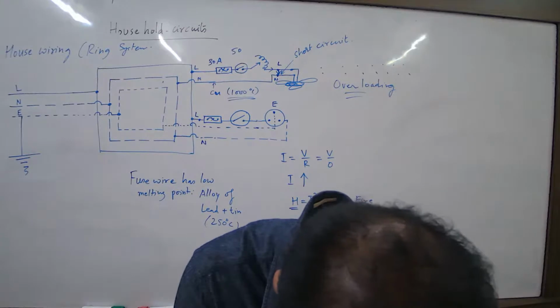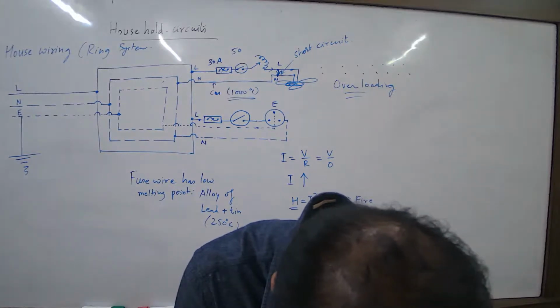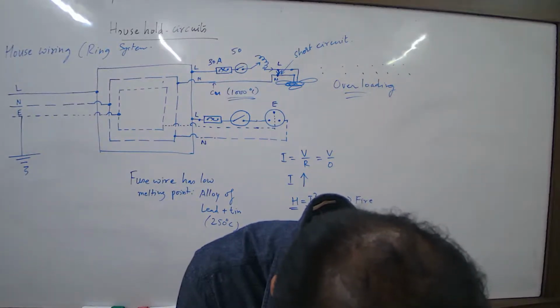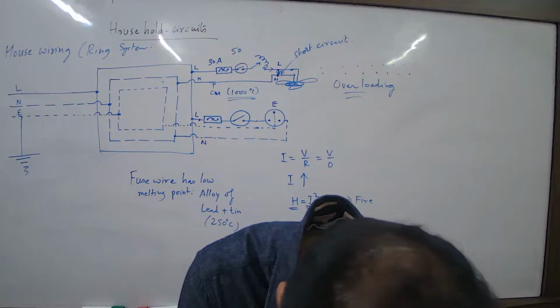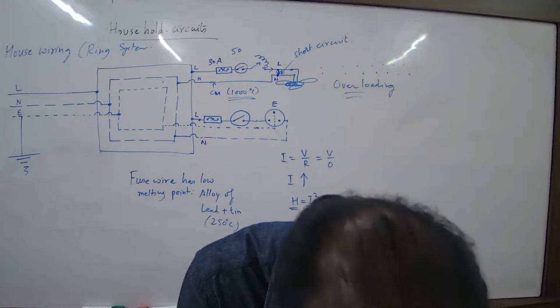Therefore, if due to some fault the fuse of one appliance burns, it does not affect the operation of the other appliances. Third, in the system, all the plugs and sockets used can be of the same size, but each socket should have its own fuse of rating suitable for the appliances to be connected there.